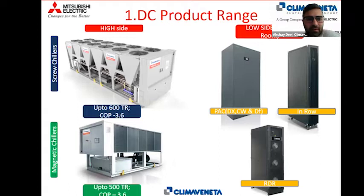Now, just a brief overview, not going into the specifics, because we want to arrive at how to improve the PUE. These are the data center products. Column number 1 is split into high side and low side just for easy reference. The high side is of course chillers, and the low side is at your server room level, which is your PAHU units. Today in the market, we have available up to 600 ton air-cooled chillers, with COPs of up to 3.6. And we also have magnetic levitation air-cooled chillers with, again, similar COPs and capacities.